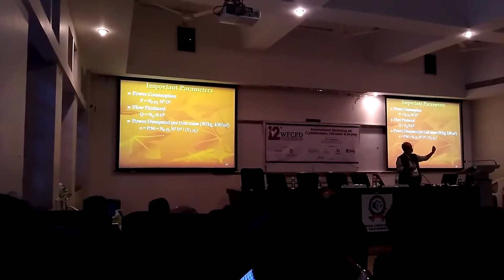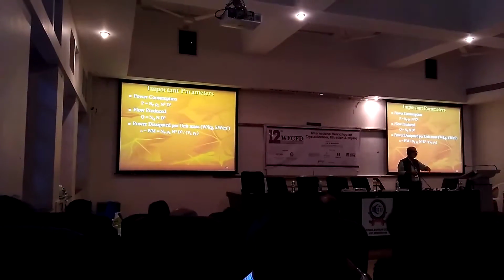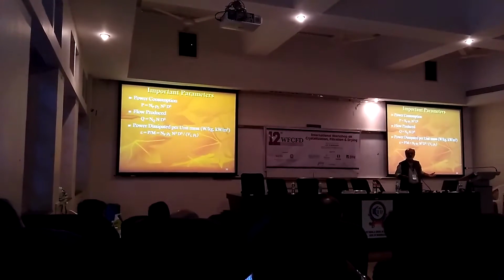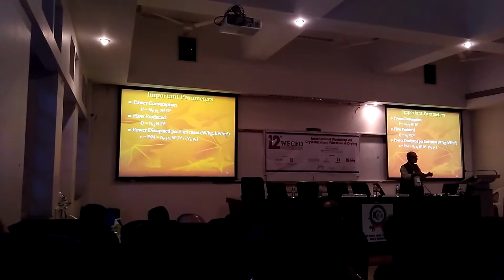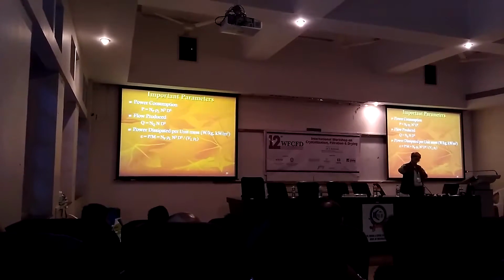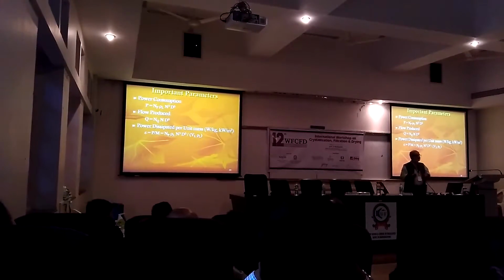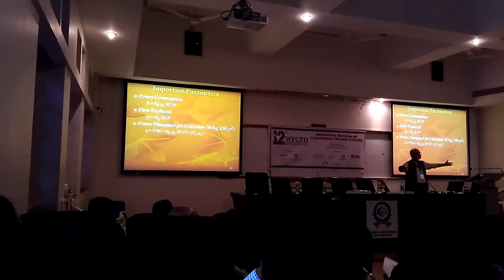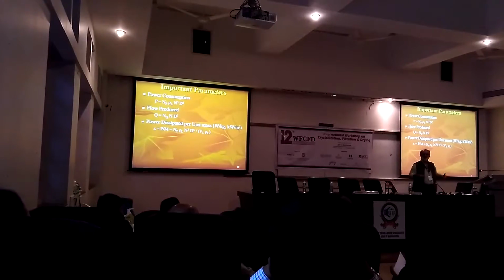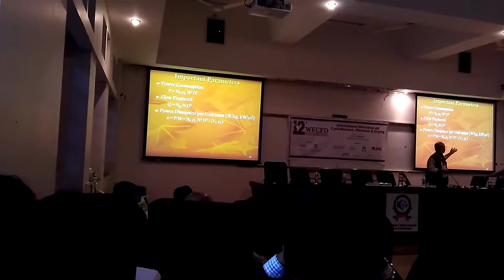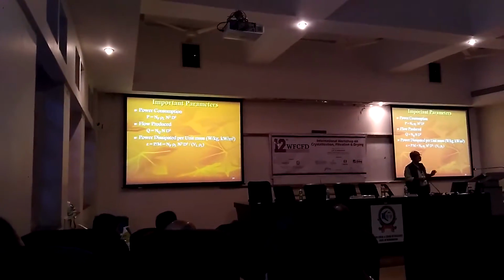You have carried out these particular experiments in a lab scale. Everything else has scaled up, but you haven't scaled up the size of your particles. The size of the particles which you are going to get and use in the lab and the size of the particles which you are going to get in an industry are going to be exactly same. So, however, you have increased the size of the vessel, you have increased the size of the impeller, you have increased the RPM of the impeller to match it. Actually, it is not going to be required because you are not scaling up the sizes of the particles.